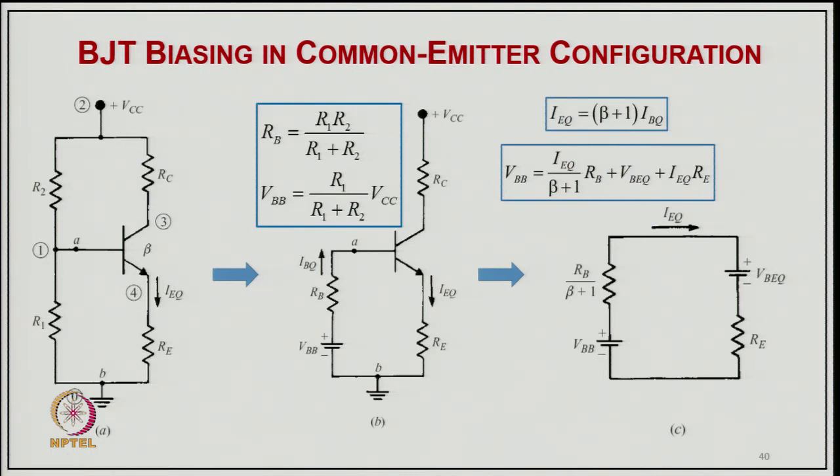So, whatever current is flowing here, if we consider this current is I times R1 upon R1 plus R2, that is the current multiplied by R1. That will be the voltage appearing as VBB, a kind of potential divider with the resistances in series. This voltage becomes almost like a Thevenin equivalent, and then you have RC as well as RE in this circuit.